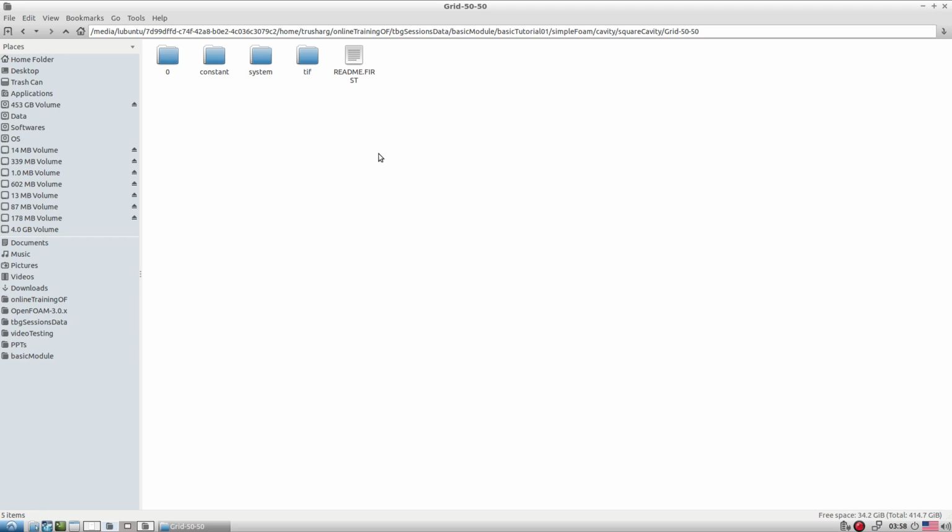What we're going to do today is explore all the entries that are available in these three files. Along with that, when we move towards fvSchemes, we explore the numerical schemes available in OpenFOAM, with the different options available, selection criteria and all these things. When we go towards the fvSolution file, we look at the different linear solvers available in OpenFOAM. So that is the idea. Let's first look at the controlDict file. So let's open that file.